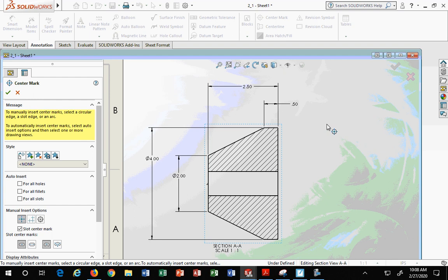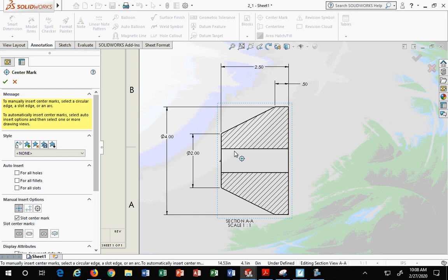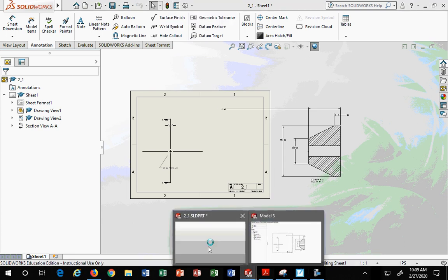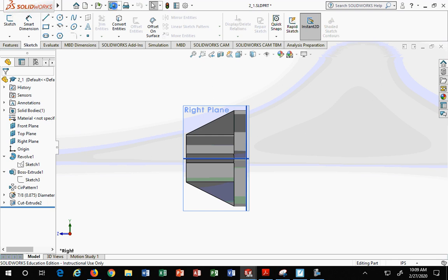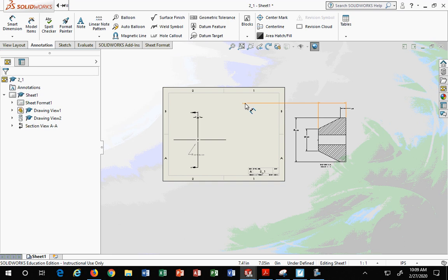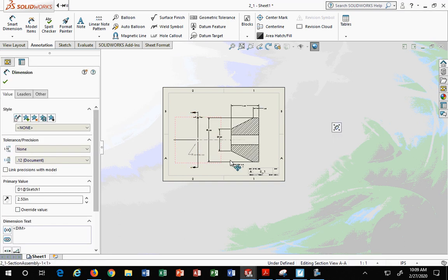So next, for those of you that know about the dimension standards, I did something bad. Hold on. All right, I think when I opened up the other part, it wants to edit what I did. So give me one second while I refresh and rebuild. All right, let me hit save. You see how they're interconnected to each other, the model. I went and edited the model, so then the detail drawing started going foobar. Those are the kind of things that will happen. The two are connected to each other.